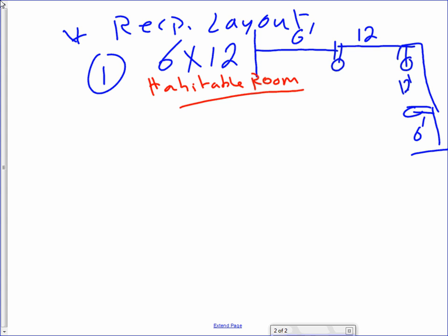Now, having said that, I told this to electricians. For you guys, as designers, your starting point when you get into the bedroom, living room, dining room, or the kitchen, as a matter of fact, is to put one receptacle in the center of every wall. Then do your measurement. Do you meet these rules? Yes, check, done. If you don't meet these rules, start adjusting these receptacles to meet the rules. If you understand this one, you will never go wrong with the design.